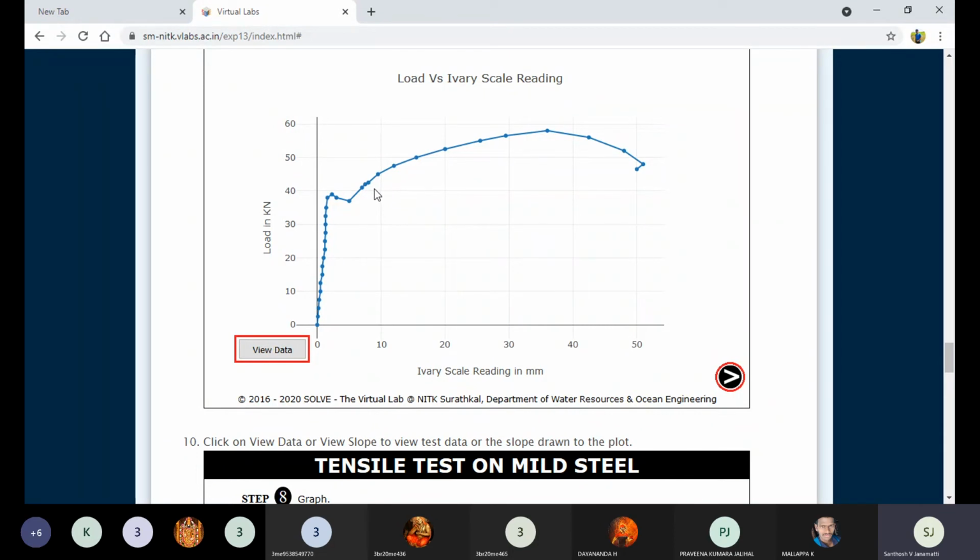Be careful, these are very important parameters, techniques, and information regarding engineering materials. The tensile test is a very important and very informative test. Once a material yields, it does not mean that the material will completely collapse, especially in ductile materials. That only happens in brittle materials. Once yield occurs in a brittle material, it means the material has completely collapsed.